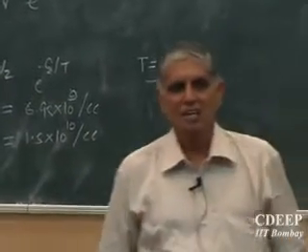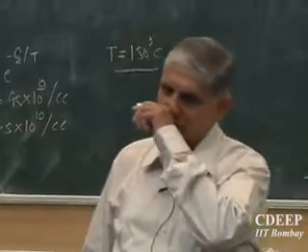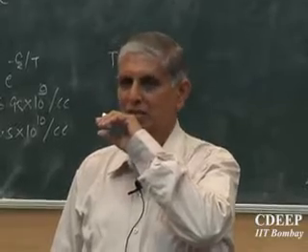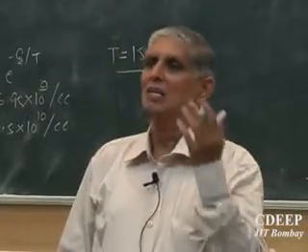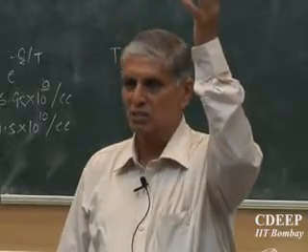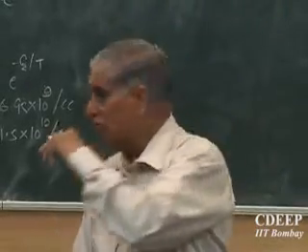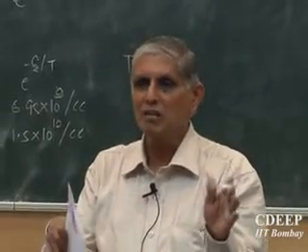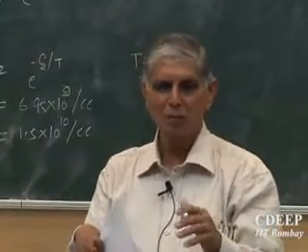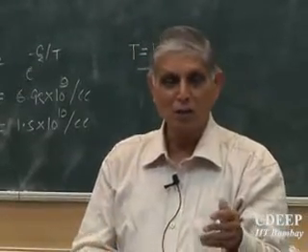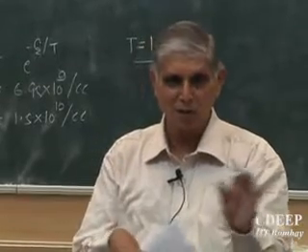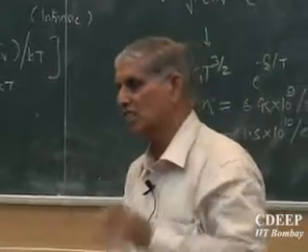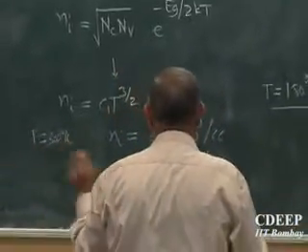So where is the discrepancy? Essentially, the Mn star and Mp star which we evaluated from the band structure are theoretical evaluations. Is that correct? They are taken from the E-k diagram. The theory itself has some limitation in solving the final equations because we are linearizing it. The second value is essentially taken from actual measurement of an intrinsic semiconductor. So we believe that since it is a measured value, it may be taken as a more universal value, but if you calculate, you may not get exactly this 1.5 into 10 to the power 10, which everyone assumes is the intrinsic carrier concentration at 300 K. Which material am I talking about? I am talking about silicon.